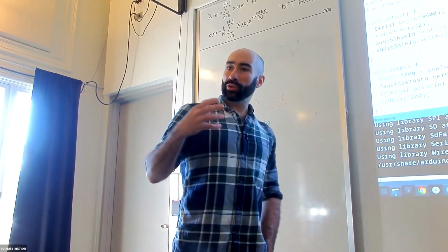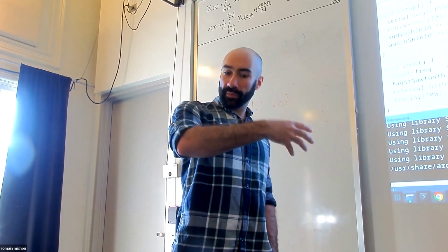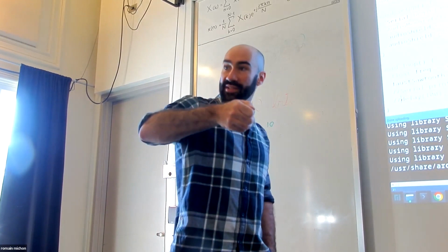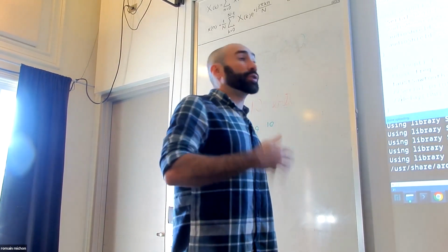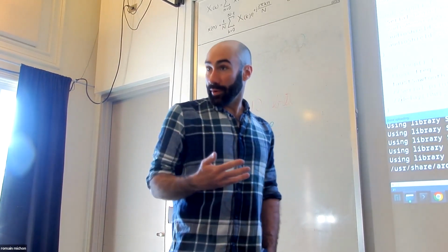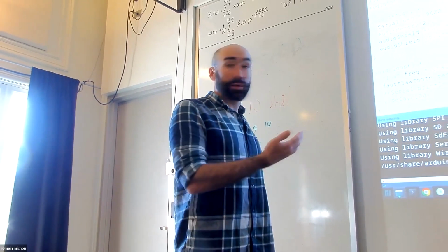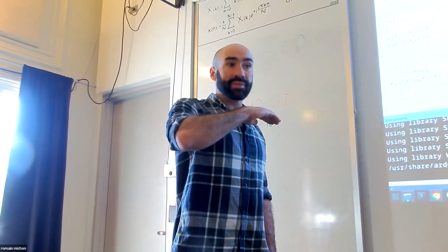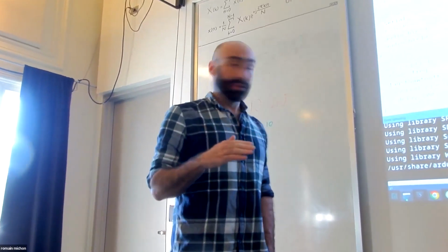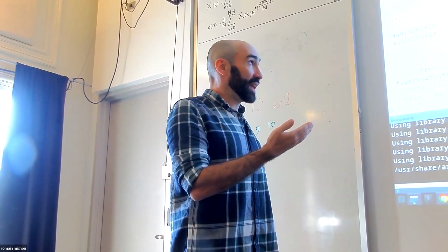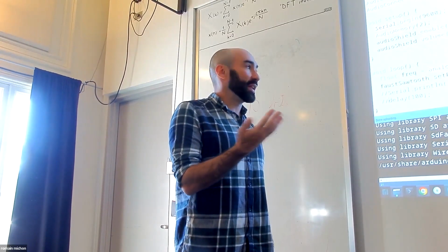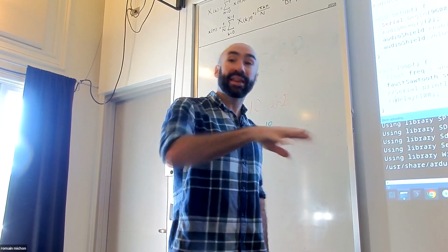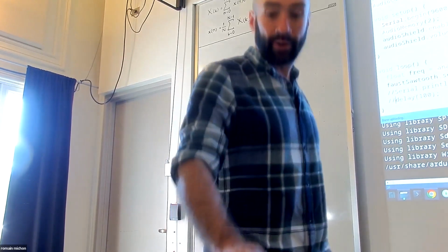But if you were to turn the Teensy into a MIDI controller that's connected to your computer and you're controlling something with the Teensy on your computer, you're going to have some latency, okay? Here, because the Teensy doesn't have an operating system, it's a system that runs completely bare metal. The latency you get here is probably inferior to 1 millisecond, which is much lower than any latency you're going to be able to get on your computer.